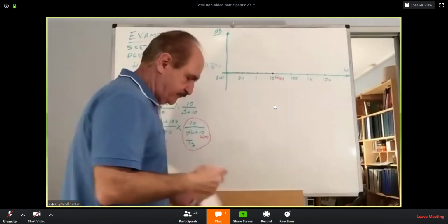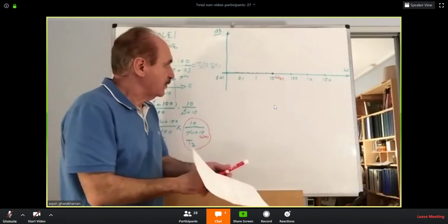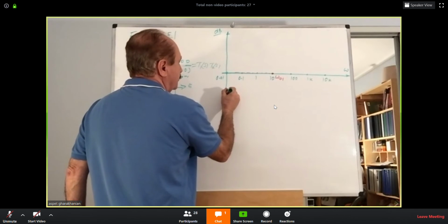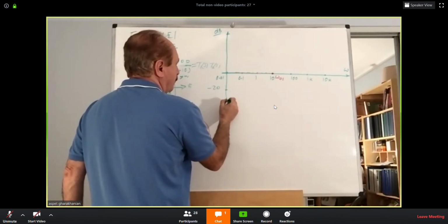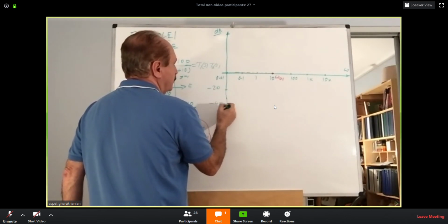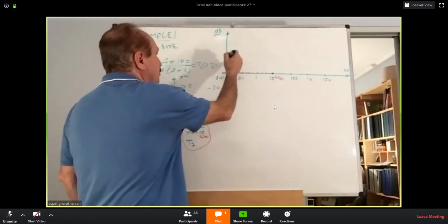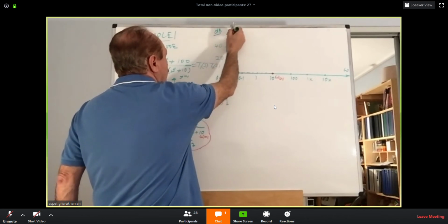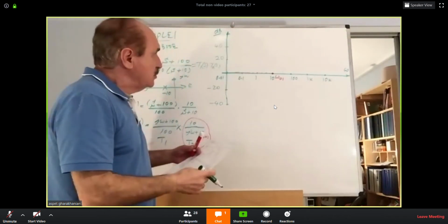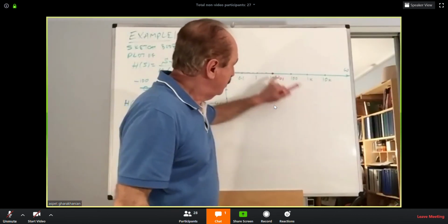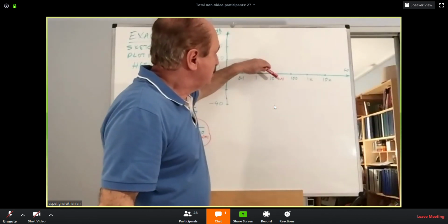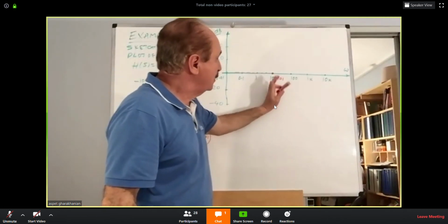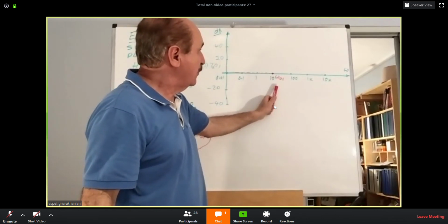The sloping. How do I create a slope? Check the scale. This is minus 20, minus 40 dB, etc., etc. And this is positive 20, positive 40 decibel. Okay, so I want to draw a line from here with a slope of falling 20 dB for every tenfold increase in the corner frequency.